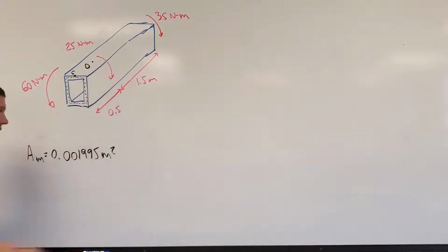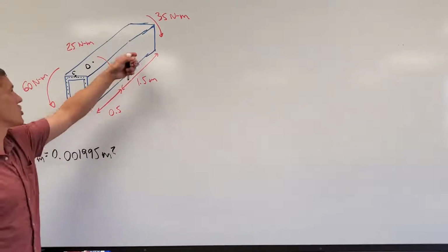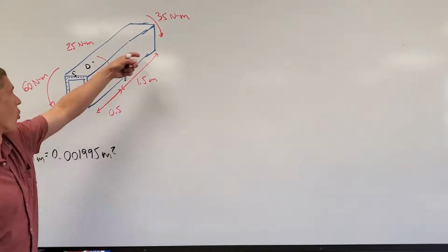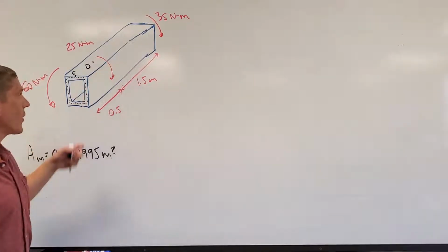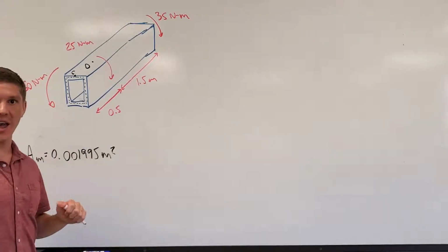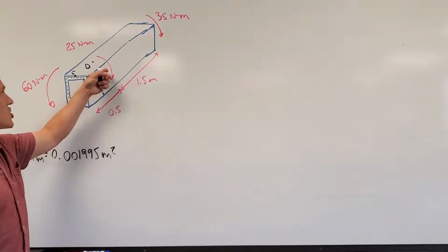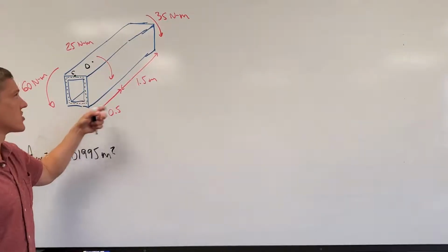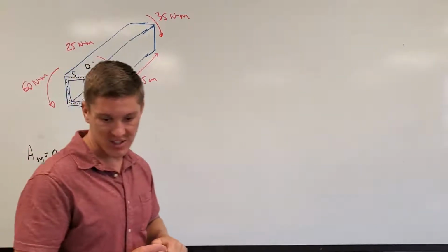We need to get good at analyzing what the torque is along different lengths of the shaft. Because they are just point torques, applied at a specific location at the wall, at C, and at D, the internal torques in between those point torques are all the same. So the internal torque is constant all the way to point D, and then it jumps, so we have a shift, and then it's constant all the way to point C. So we have 35, and then we have 60.